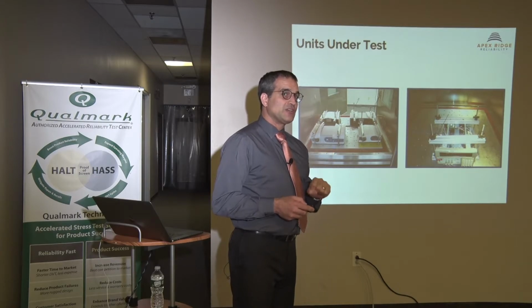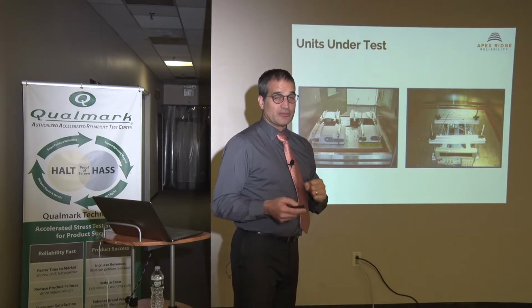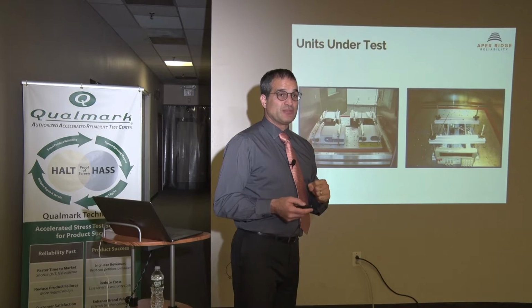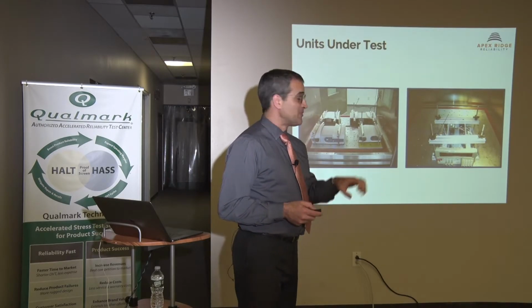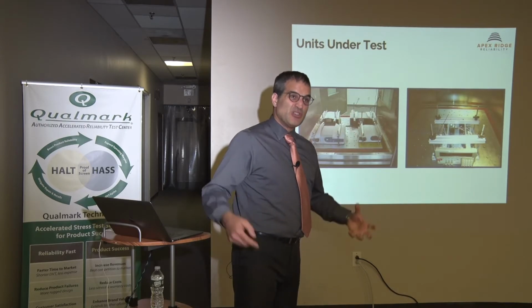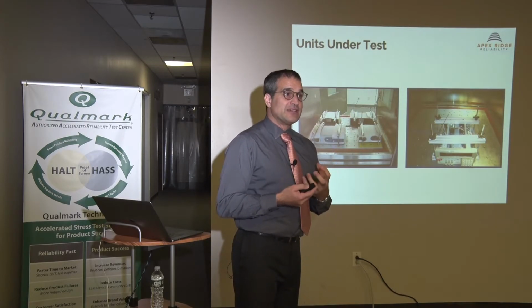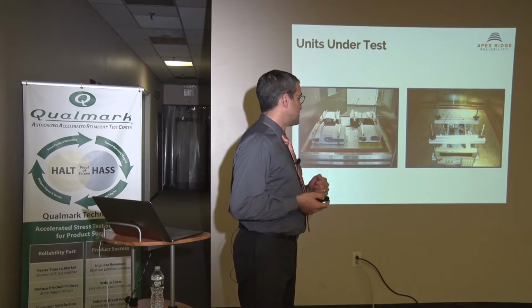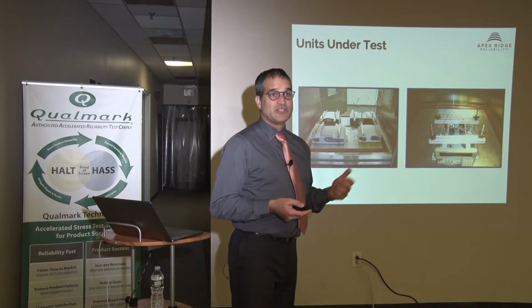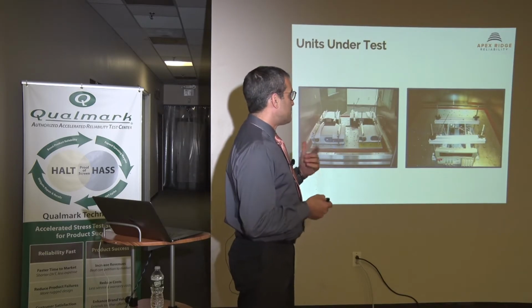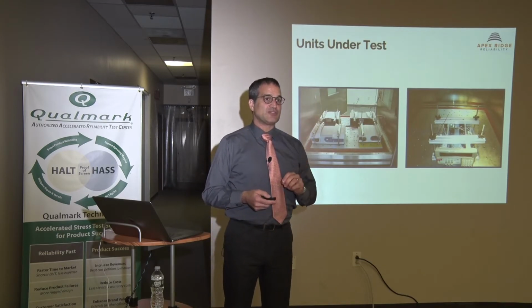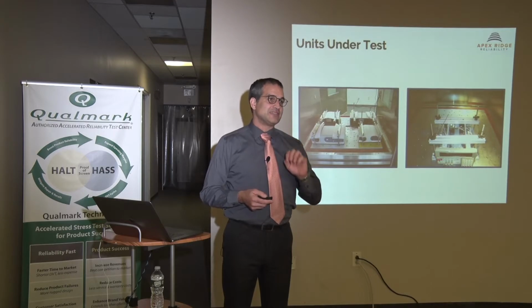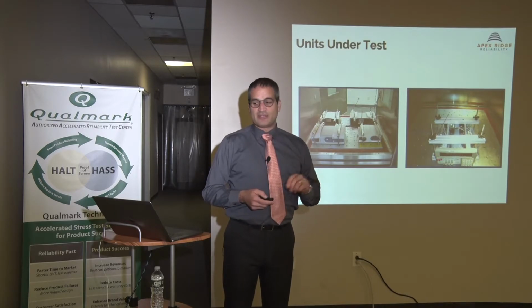And again, we're not looking to see how the product will operate in normal conditions. We're looking to create extreme stress. That's why you take the cover off, so you can do temperature changes even faster. That's why you clamp it hard to the table, so you can get that vibration energy into it. None of that is how this product will really be used. You can see this is something that would probably just be on a shelf in a lab. But by allowing vibration and temperature extremes to get in there in the chamber as quickly as possible, it's the same thing as putting the dynamite in the rocket cone.